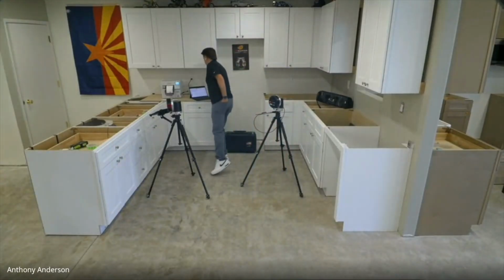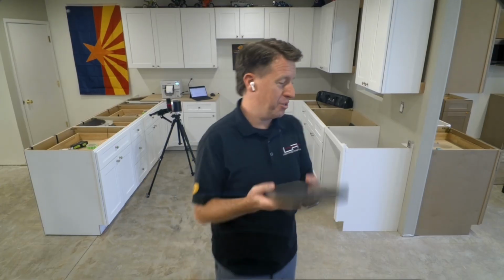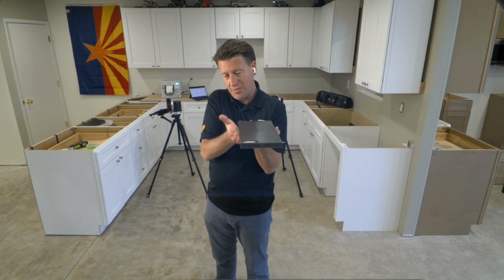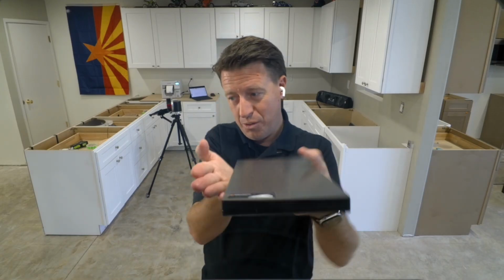There's another trick that you're bringing up too. Like you're bringing up miters. So cleaning's almost done, I think. Another thing that's worth talking about is I might do more blade kerf on a miter. Dustin, is that something you see is pretty common? Because that miter, when you have your material, as soon as your blade's coming in at an angle, we aren't measuring the blade by the thickness this way. We're measuring it like this. So it's quite common.